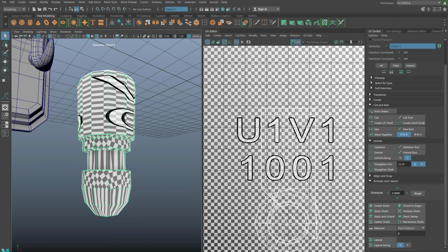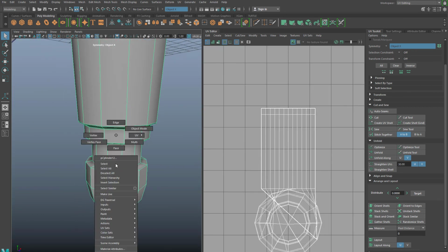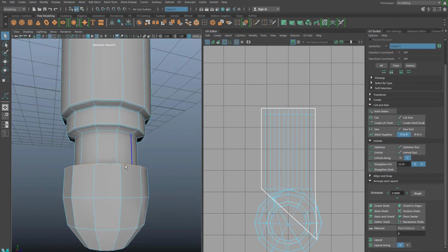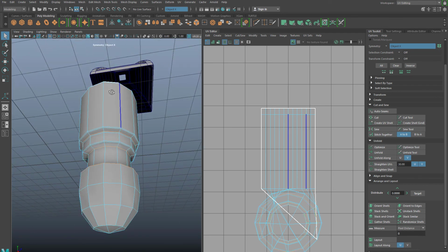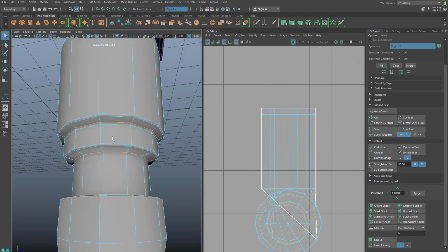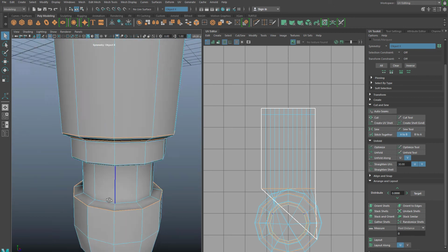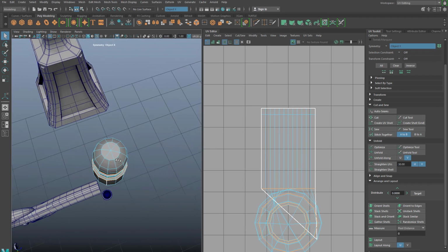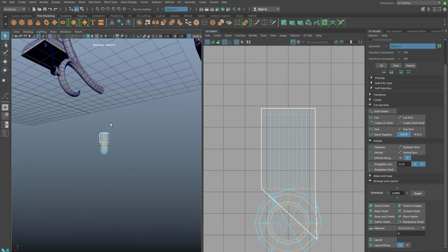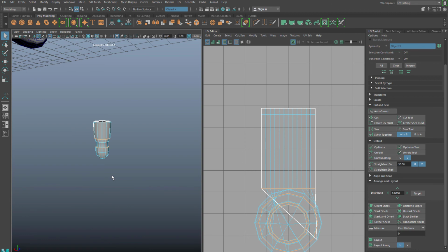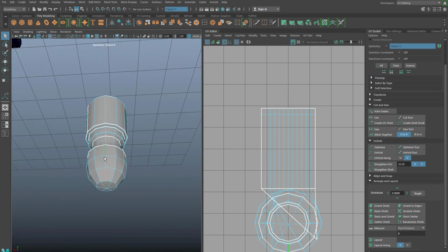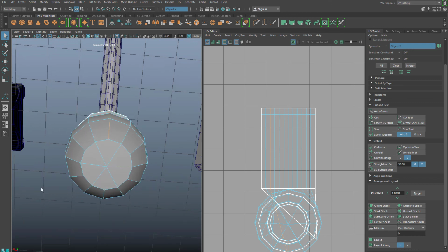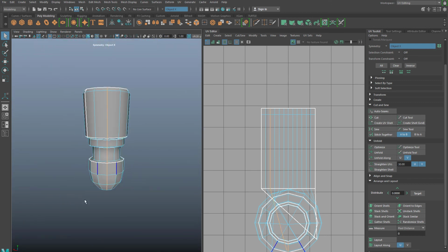On the bottom down here, turn off the grid. Cut the large cylinder off, have the middle cylinder, have the inside cylinder, and then we'll have the cone cap. And then what I want to choose is, since we'd probably be facing the object this direction, what I really want to do is find this back edge right here, select that, and go ahead and cut.